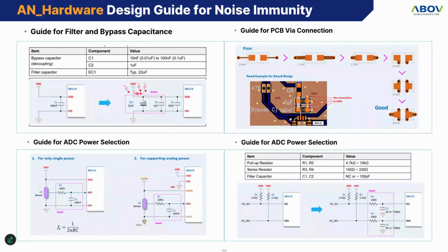The noise immunity hardware design guide advises on reset, I2C, and ADC, those noise-sensitive ones in circuit design. It details PCB structure, layer connections, and power line layout for noise reduction. You should refer to the hardware setup guide for more information. Also consider leaving extra room for your PCB layout for future PCB modification when the noise issues cannot be solved in the future.